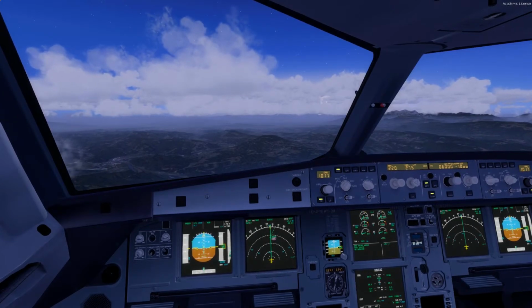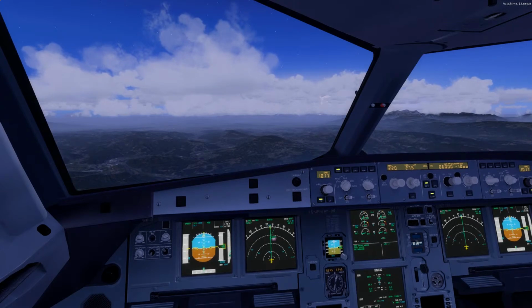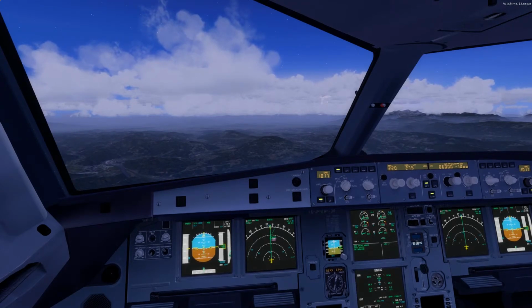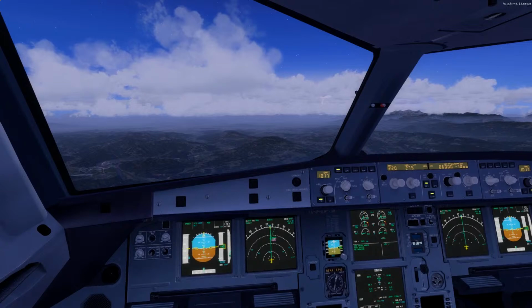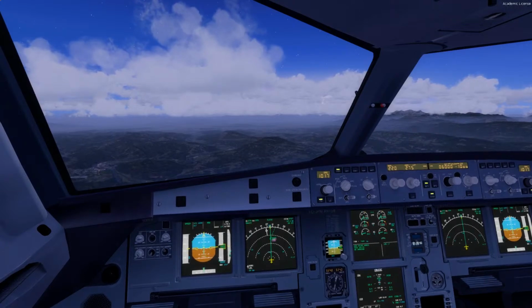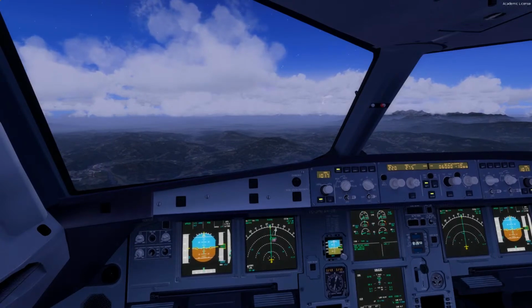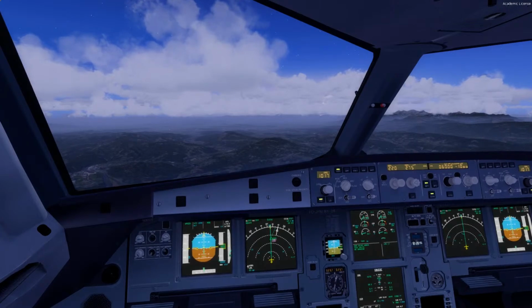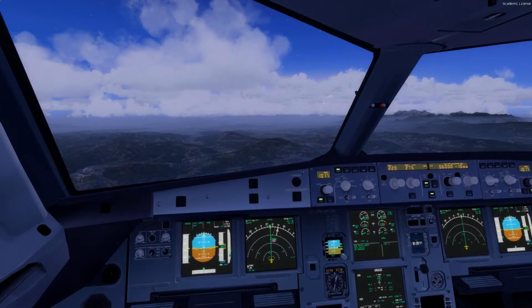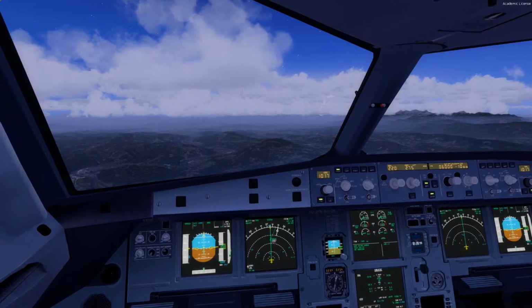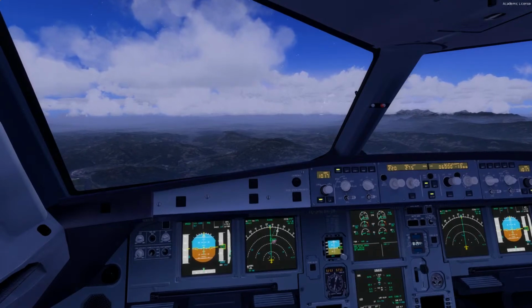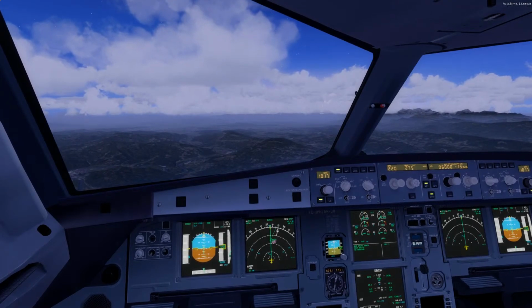Now we will slow down more to reach Dolsko, which is Delta Oscar Lima VOR station, and we will probably overfly it, which is somewhere in the halfway to the point we will intercept the localizer. So we are continuing with the descent to 6000 feet.